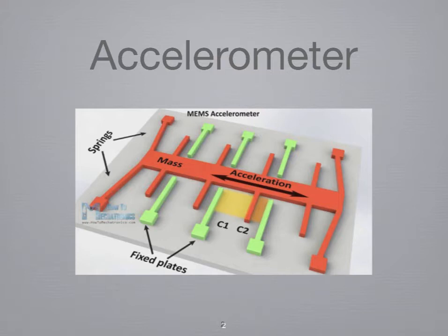The frequency response of accelerometers is particularly important in vibration measurement in view of the inherently high frequency characteristics of the modern situation. The bandwidth of both potentiometer-based accelerometers and accelerometers using variable inductance type displacement transducers only goes up to 25 Hertz. Accelerometers that include either the LVDT or strain gauges can measure frequencies up to 150 Hertz. The latest instruments using piezo-resistive strain gauges have bandwidths up to 2 kilohertz. Finally, inclusion of a piezoelectric crystal displacement transducer yields an instrument with a bandwidth that can be as high as 7 kilohertz.